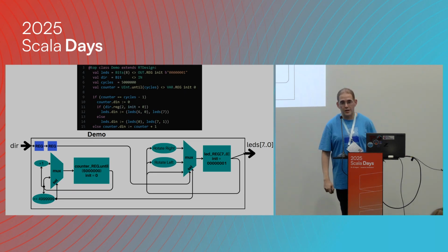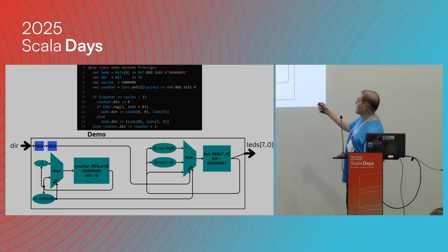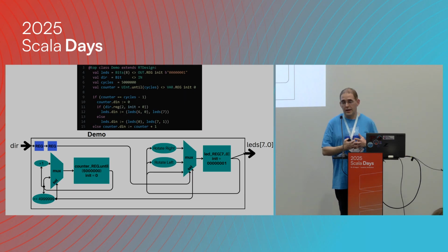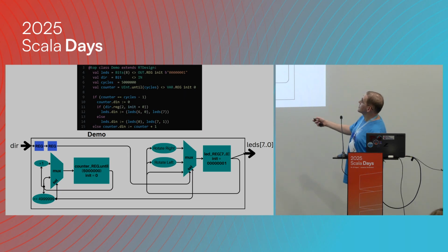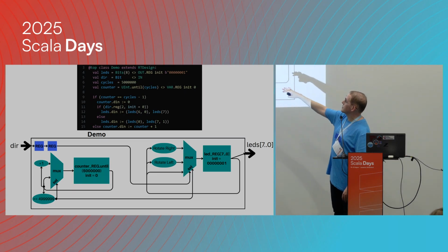So I talked about the register. What is a register? So a sequential circuit has a clock, and it has a component called a register. A register only always saves a value, and it only changes its output when the clock ticks, in this case, in the rising edge tick. Then the input of the register gets transferred to the output of the register. Until the next clock tick, the register preserves its value.